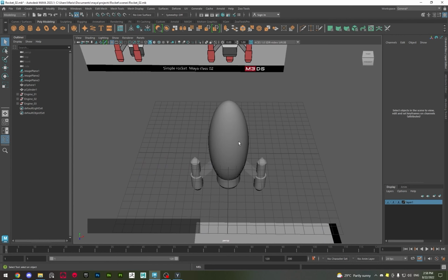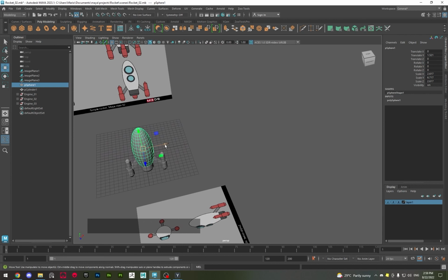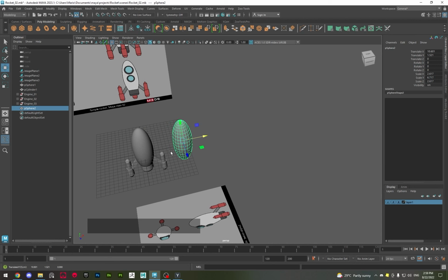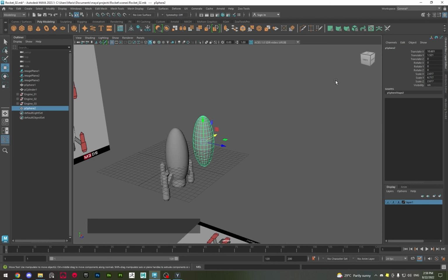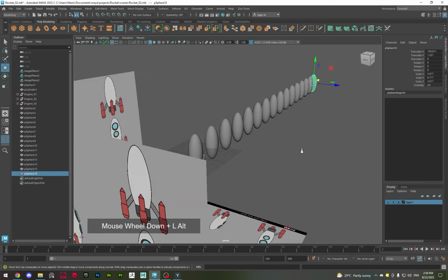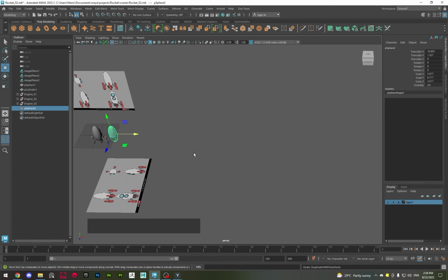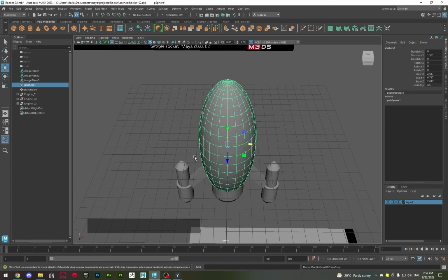So, for example, let's just say I want this sphere to make 50 in a row. I'm going to press Shift D, move it, and if I want all 50 to be moved that way for this same distance, I'm just gonna keep on clicking Shift D, and it's gonna keep on creating them for the same distance. This is going to be very often used later on.